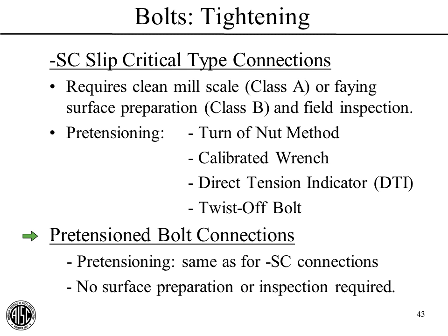There's actually a 4th kind of connection that I'll call just a pretensioned bolted connection. In this case, we just need the bolts pretensioned for some reason, but we don't need an SC connection. So we have the same pretensioning requirement, but we don't have any surface preparation or inspection like up here for the slip critical connections.